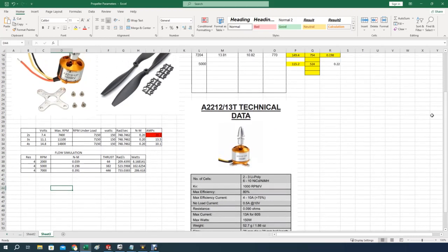So what I'm planning to do is repeat this calculation, but doing that fully automated, so that the system will pick for me the proper RPM and will calculate until we hit the 150. Certainly, you can do here in manual. You can do an interpolation and come out with the proper value that you need for 150, based on that 5,000 is 102, 7,000 is 286. So you can interpolate to get the 150. What is the RPM required for 150, which definitely will be above 5,000 but below 7,000. You can do that. Now, here's the story.